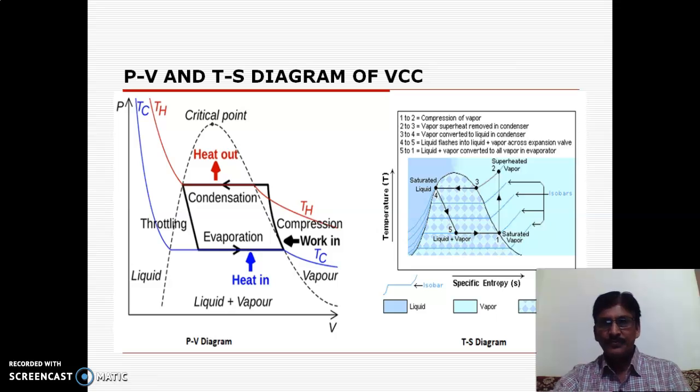So in the vapor compression cycle, the analysis of any vapor compression cycle is very important. That is based on your basic values of enthalpy, that is total heat content, which we need to find out. So for finding this we require different charts of refrigerants for finding the enthalpies. For different refrigerants, we use different pH charts for finding the COP of the system.